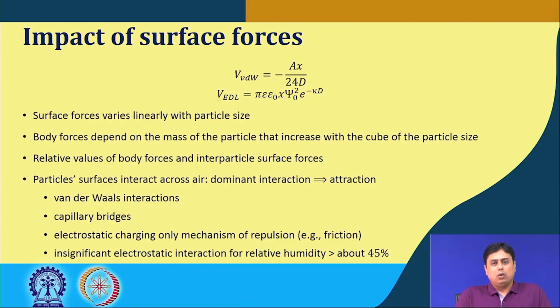Now, this is the overview on the overall forces, and how it impacts handling the solids, the particles or the colloids. We have seen the potential energy for the van der Waals and the electrical double layer. From both expressions it is clear that the surface force varies linearly with the particle size, where x is the particle size.